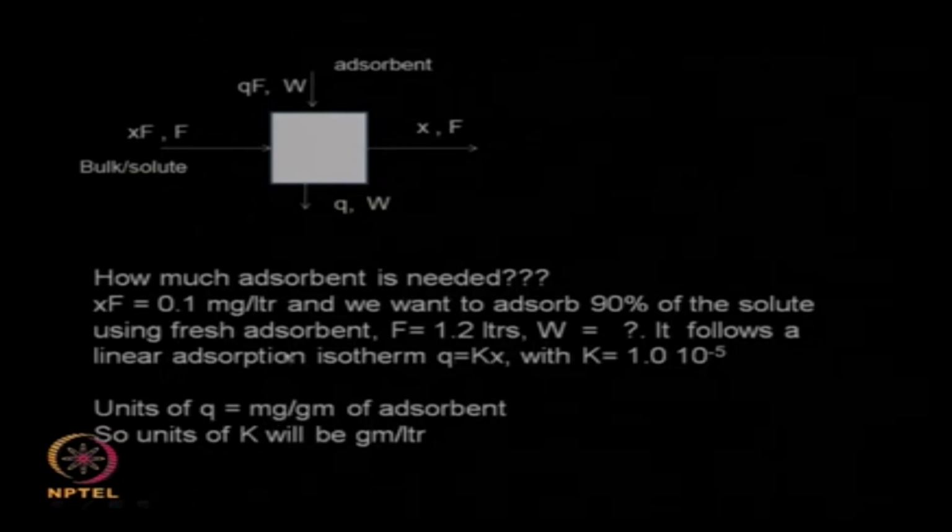In this particular case, K will be in grams per liter, because Q will be in milligrams per gram and X will be in milligrams per liter. So, the units of K should match with the units of X and the units of Q.